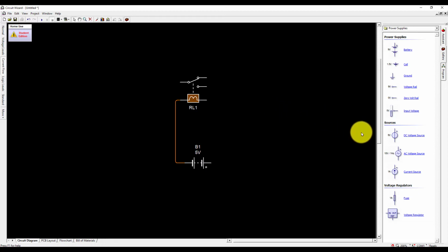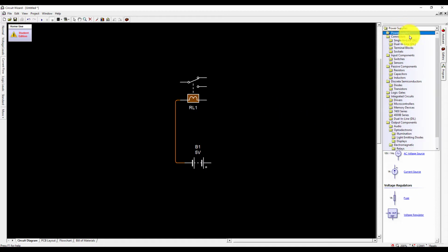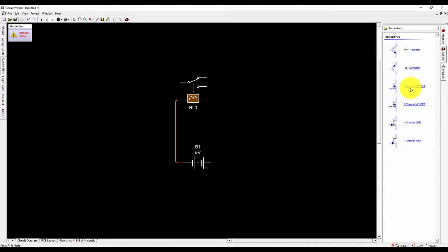Now we use a transistor called an NPN transistor. So I will look for a transistor. Where are the transistors? There they are. This is my NPN transistor. Remove this wire and put the transistor on this side, flip the transistor this way, connect the negative pin to the transistor here, and this will go to this pin of the transistor. Directly connect the positive pin to the relay.